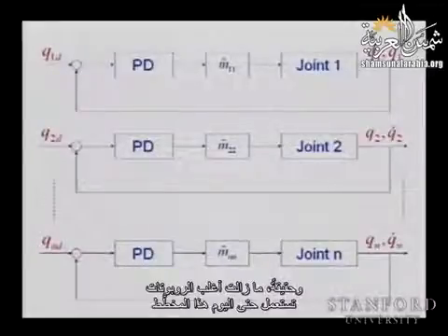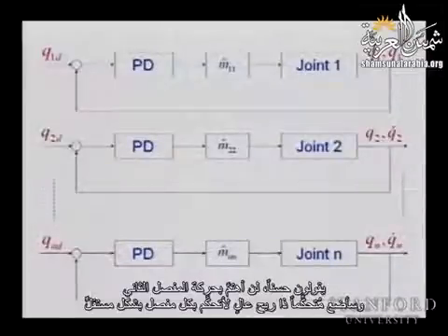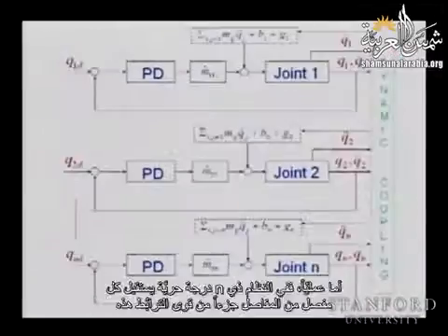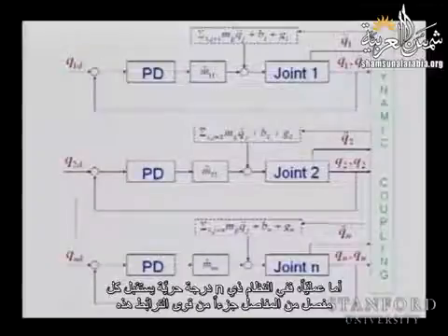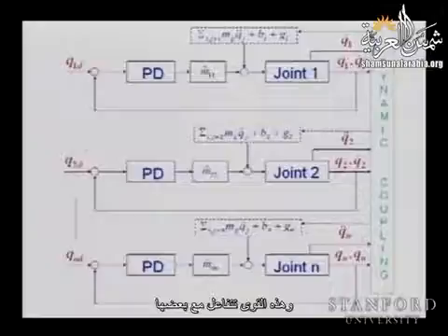In fact, most robots today in industry still use this scheme. They say, okay, I'm not going to care about the motion of joint 2. I'm going to put a controller with large gains so I can control each of the joints separately. Whereas in reality, in the n degree of freedom system, each of those joints is receiving those coupling forces, and these coupling forces are interacting.